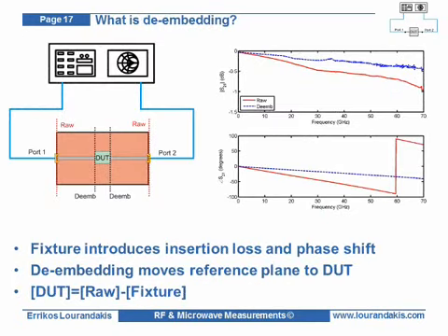As we mentioned before, after the calibration is completed, we are ready to perform the actual DUT measurement. As it is often the case, our device under test is a small passive or active circuit or module, which has to be mounted on a PCB with coaxial connectors and feed lines. These feed lines, although necessary for performing the physical measurement, are distorting the actual DUT performance by inserting some loss and phase shift. This unwanted contribution of the feed lines can be removed by another mathematical procedure known as de-embedding.